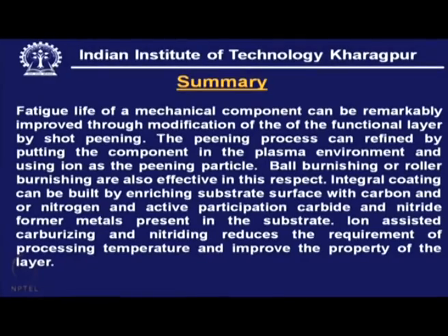What we can summarize here is that the fatigue life of a mechanical component can be remarkably improved through modification of the functional layer by shot peening.